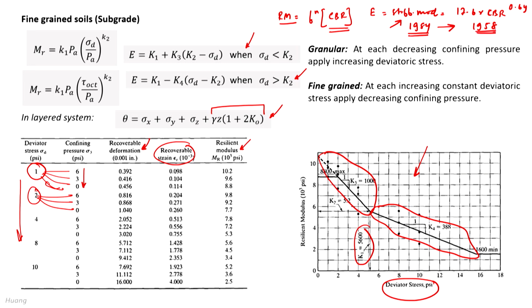So, you can see that long back the researchers had already worked on these aspects for developing the correlation, and the original equation which you see here is valid for a CBR of 2 to 12%, and in fact this equation is also used in India, but we use this equation when the CBR value is more than 5%. Okay. So, for 2 to 12%, the equation as I showed you is also used in the UK pavement design.